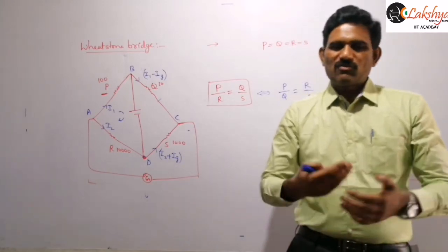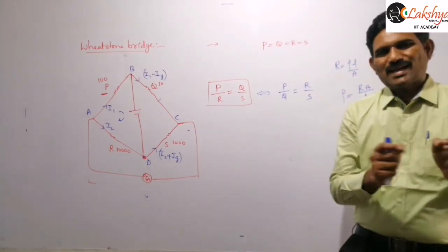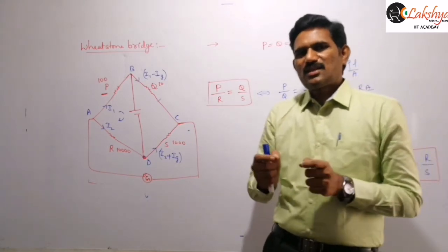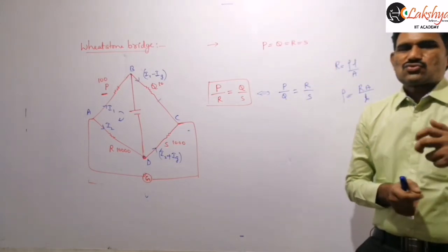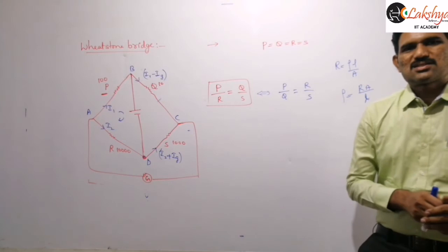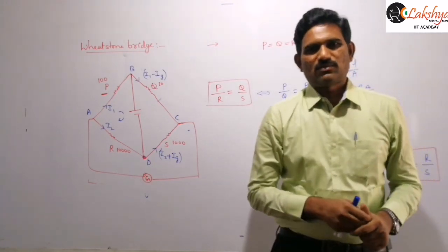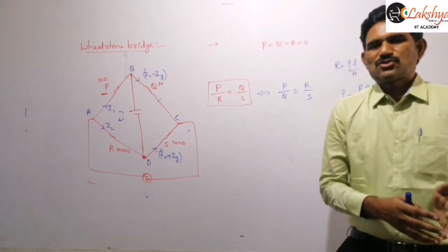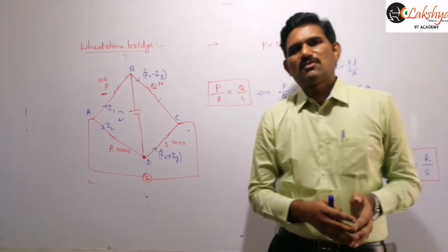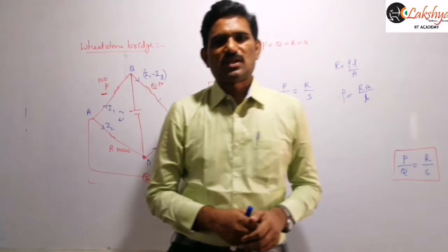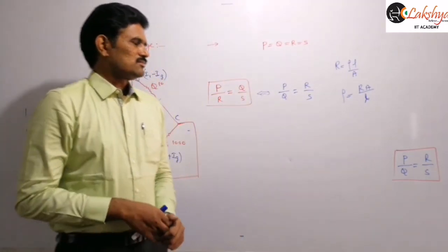So just by measuring the change in that resistance, we can find how much the wire is stretched. We connect the wire in the Wheatstone bridge, and again we find its resistance. So we can calculate how much change there is in the resistance of that wire. Just by finding the change in the resistance of the wire, we can estimate how much strain is produced in that wire, right? Because we know the relation of how the resistance depends on the area of cross section and on the length of the wire, right?